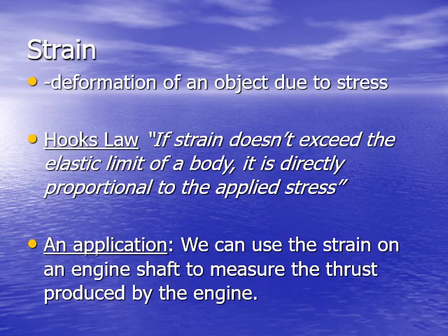Strain is the deformation caused by stress. According to Hooke's law, if the strain is within the elastic limit, it is directly proportional to the stress applied. This principle is used in designing engine shafts, wing spars, and detecting structural fatigue.